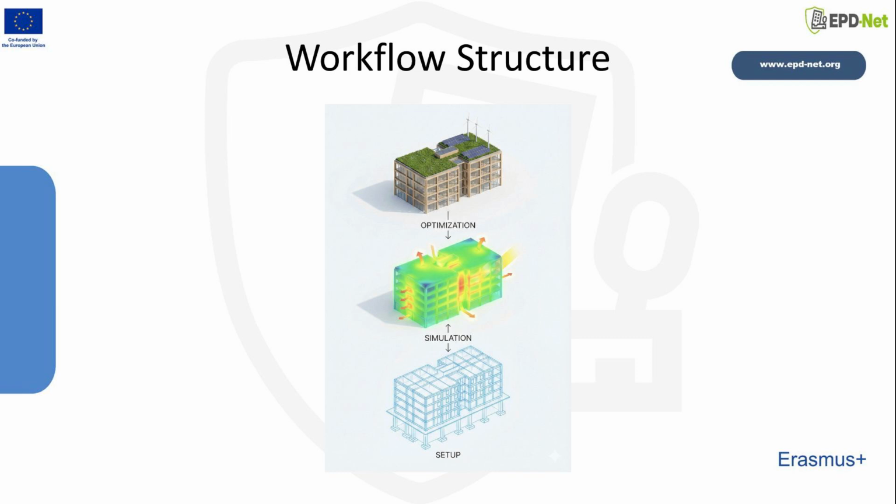Two types of evaluation can be conducted: real-time performance evaluation. Simulation plugins connect the variable geometric model, e.g., created in Rhino, Grasshopper, to established energy simulation engines like EnergyPlus, or daylighting engines like Radiance. This allows for the real-time evaluation of how changes in parameters affect performance metrics.